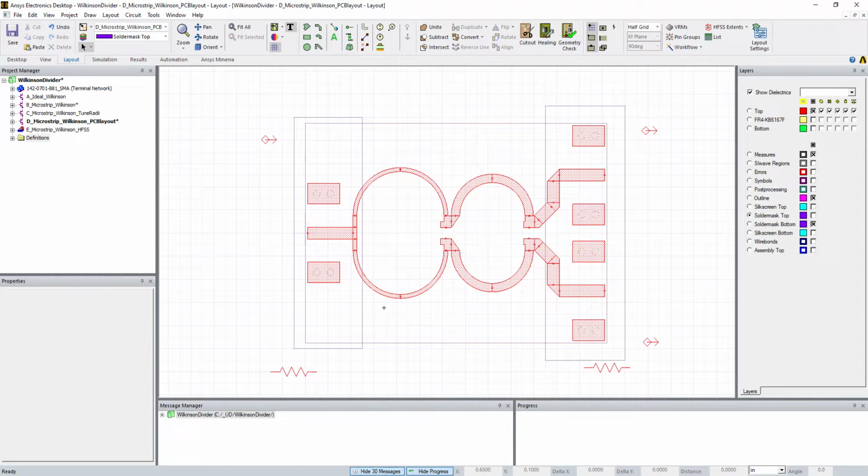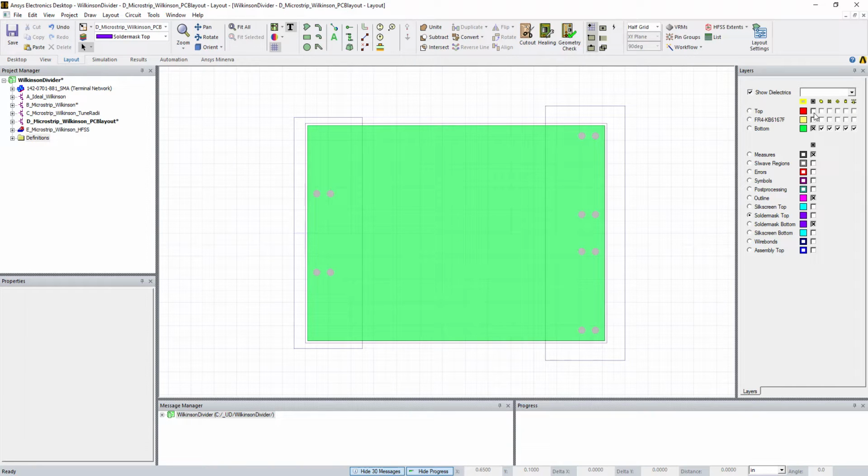This is underneath the board, again, now we're looking at the bottom layer. I'm not looking at the top layer anymore. So this is the bottom layer. I just need this to be free of solder mask. This can have solder mask on it. Who cares? And it will. So it'll literally have solder mask from that point all the way to this point, and no solder mask here. Why did I do that? Because if I wanted to put some silk screen, I could do that.